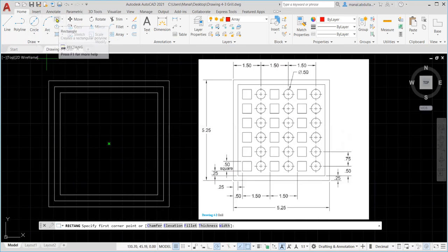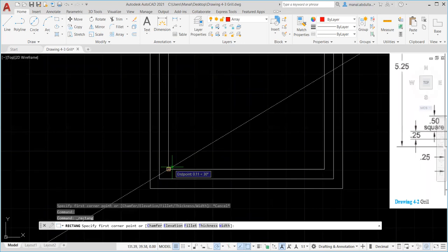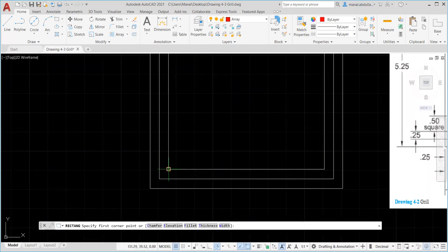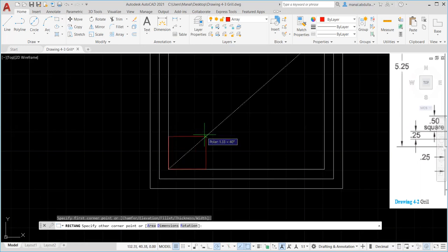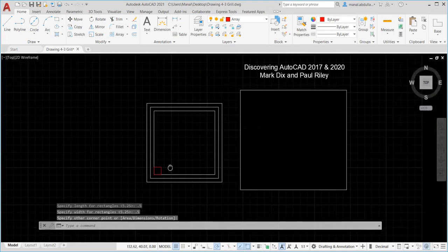I need to draw a square, and I'll zoom in here a little bit so you see it. I'll pick that point. Okay, so again, square, pick the point accurately. Now from here, you put dimension, and the first dimension is 0.5, enter, then 0.5, enter. Then see here, you need to put direction. Where do you want to go? I put it inside. So here you go.